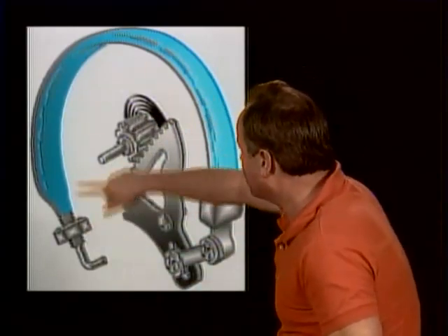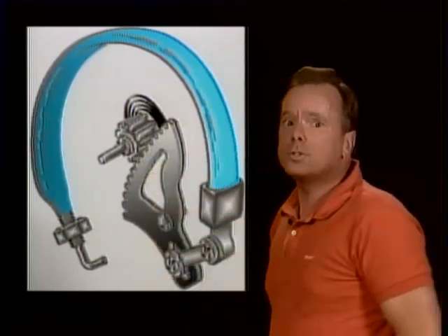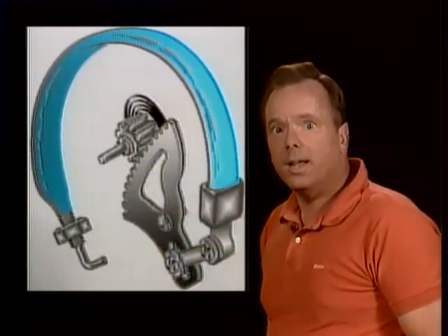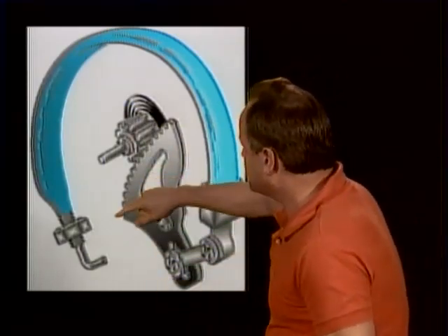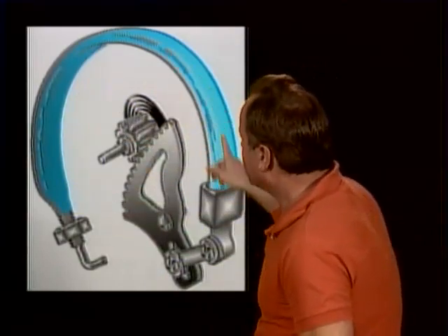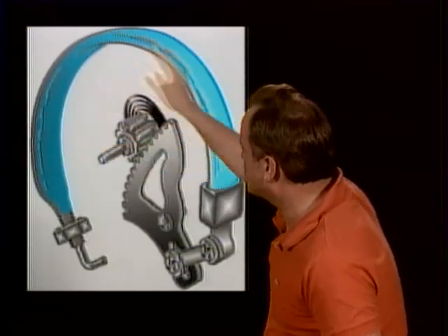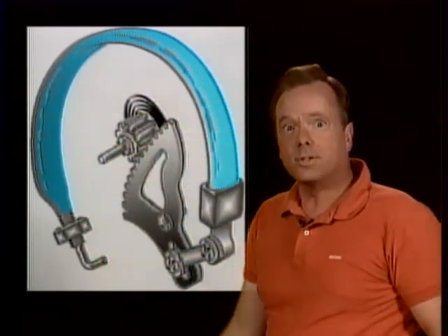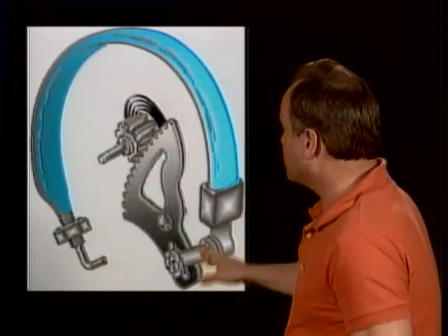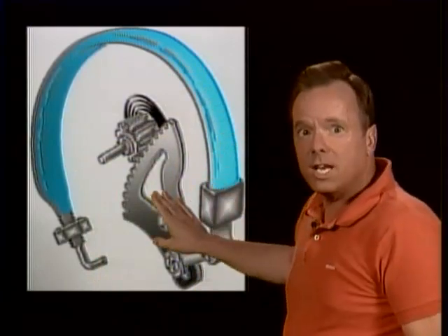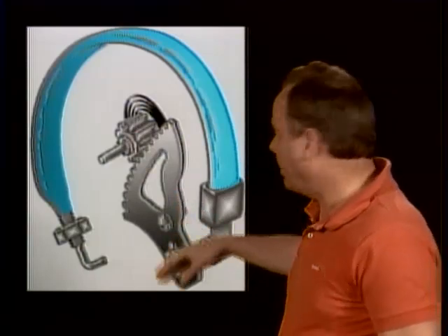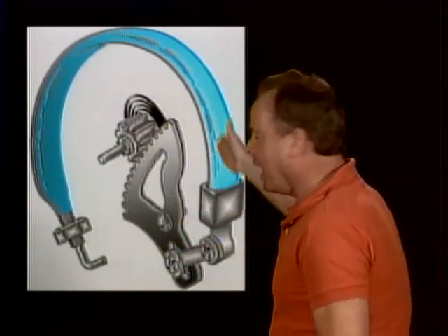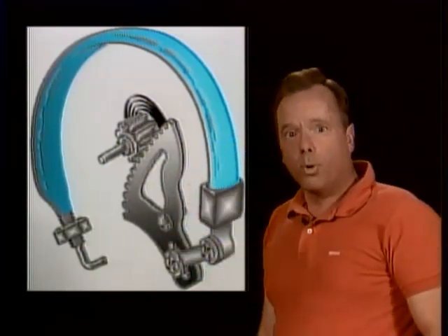And that's called a Bourdon tube, and it indicates pressure. You can also use this to indicate temperature, by the way. The way you do that is you put a very volatile fluid in here, and when the temperature increases, the pressure increases, and once again, it tends to straighten out this tube. So you can indicate pressure or temperature, but oil pressure gauges tend to be the Bourdon type, and if you have more than 10 psi, the FAA wants you to know, you'd probably use a Bourdon type gauge.